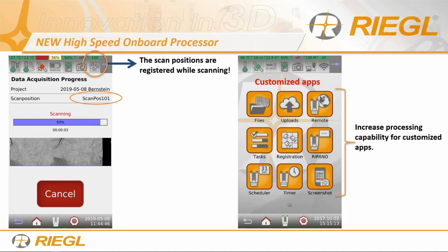It's beautiful. Our scanner used to take 10 minutes to do a Panorama 40, which is 6.5 centimeters at 100 meters. Now it does that in 45 seconds. And with that, you can really talk about productivity now versus the technology, right? So the technology has been proven. I think it's been accepted. It's been used. It's been tested. It's been brought through the ringer by all departments: engineering, surveying, departments, DOTs to USGS.